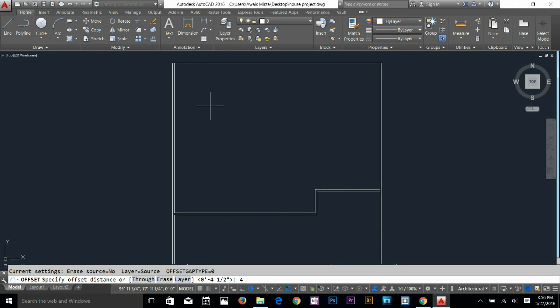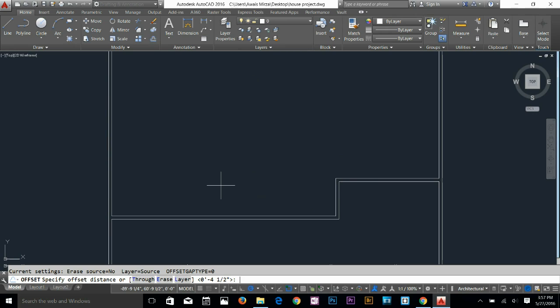Okay, I'm going to give another offset of 4.5 inch from the back to up. So now let's make a room from the left. I'm going to give a room of, let's say, 15 feet. This is going to be a bigger room to the right, and offset 4.5 inch. So for the 2D planning at the basic level, all you've got to use is the fillet, offset, and trim commands, and some basic commands such as rectangle, line, and polyline, right?